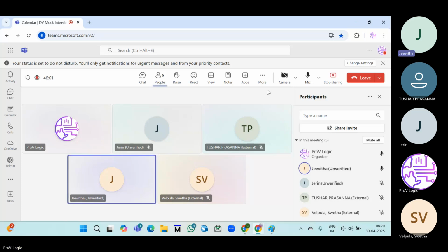Reset is generally nothing but forcing a design to a known condition after powering up. There are two types of resets: synchronous reset and asynchronous reset. If you specify it in an always @(posedge clock) block, that is a synchronous reset. Reset will happen only when it is synced with the clock. That is called synchronous reset.